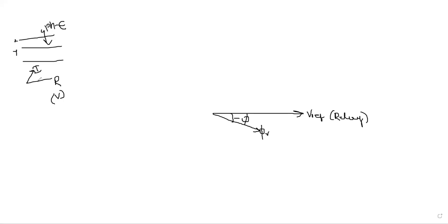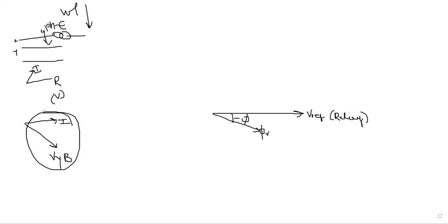But let's assume my R phase fault occurred near the potential transformer, near these PTs. Then the voltage will collapse. Voltage is very low, so I cannot compare the fault phase current to the fault phase voltage. Obviously we have to compare the fault current with respect to the healthy phase voltage, V_YB. So for an R phase fault, Y and B give the reference voltage.